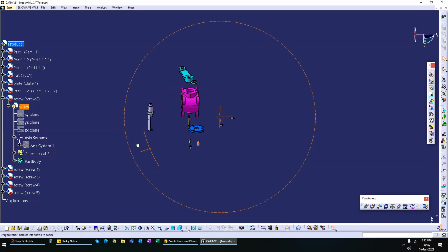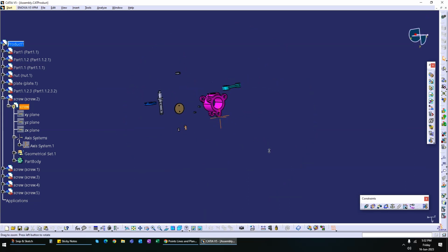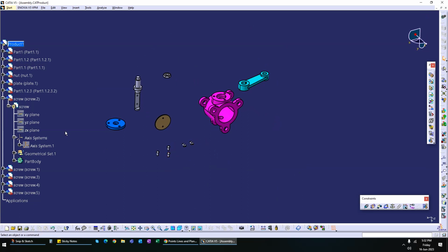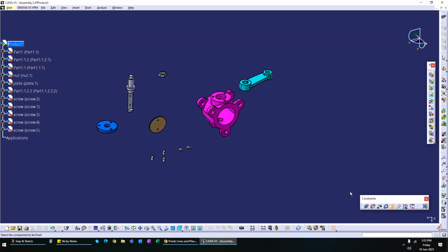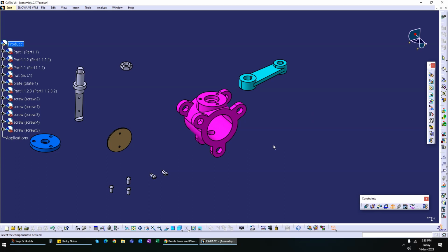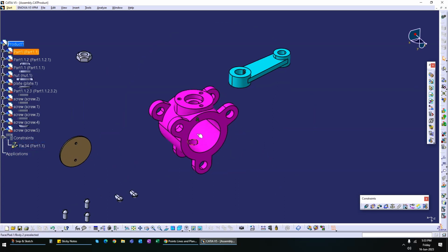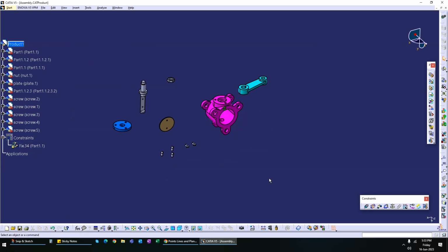Okay. First thing is we need a base part to which we are going to attach all the other parts, and to make sure our base part doesn't move, we use this fix component. What fix will do is it will fix all 6 components of degree of freedom. There will be no freedom for this part to move anywhere. So it has fixed it, and we can consider this our absolute zero as of now.